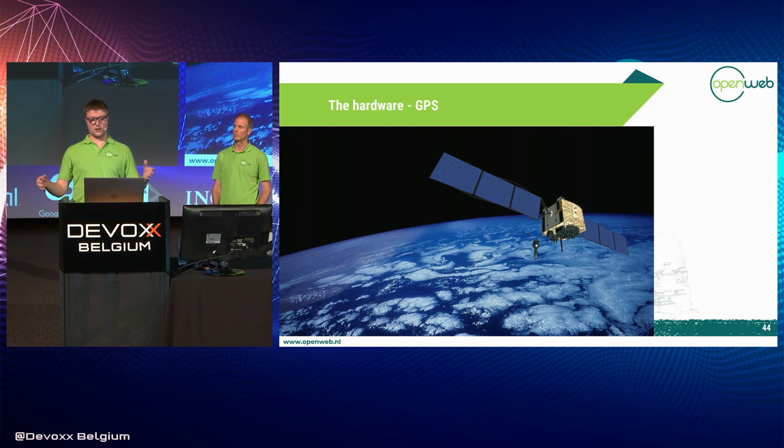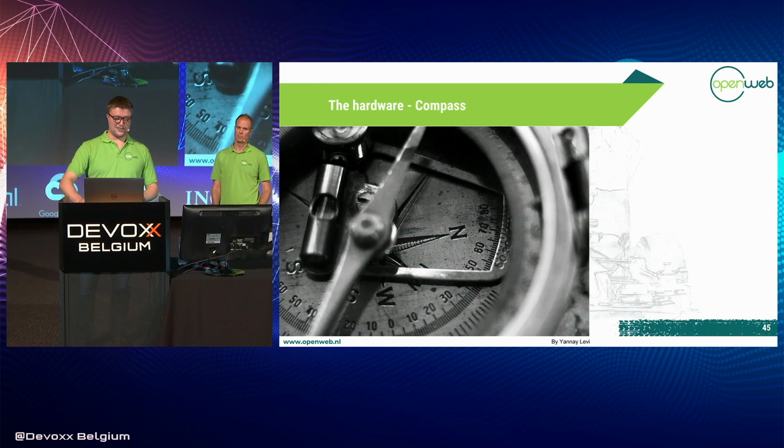Figuring out which message we have to use, how to decipher them, and comply with the encodings that tell us if the line is correct was a bit of a hassle, as was configuring the Raspberry itself to be able to communicate with this device. But after we changed the settings and got it working, we have a GPS now. Then we get to the compass. The compass was for some reason much easier than the GPS.